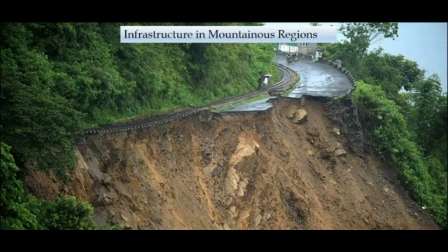And what you see over here is a very interesting thing. Over here, you can see that the exposed surface comprises rocks and soil. The soil which you see is basically weathered rock or rock mass, which has eventually been converted into a soil-like material. But mostly the failure surface, when you visit the site, you will see that it mostly comprises rocky strata.